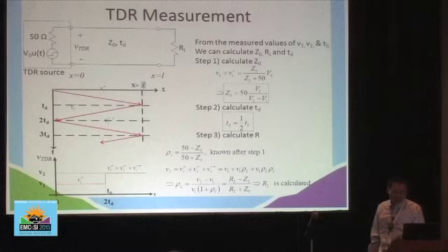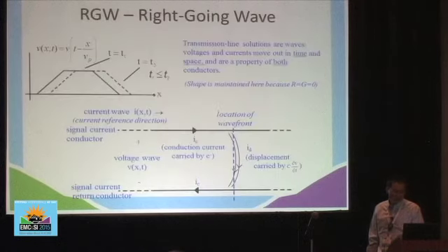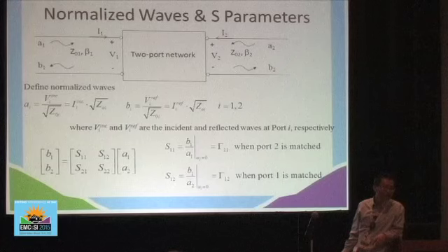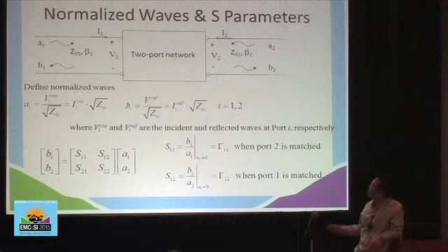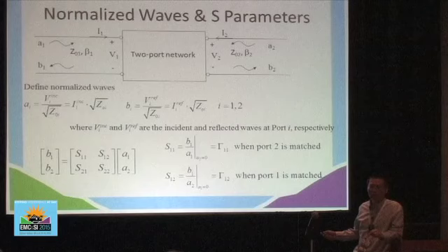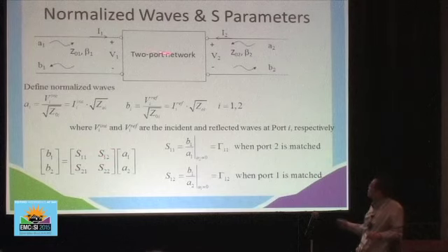The insertion loss and the reflection loss, that's a good question. It's actually a frequency domain concept. It's actually in here when we talk about the S parameters. Okay, so when you put some device into your measurements, if you see a reflection at one of the ports, if we take the log definition, we usually call it the return loss. Okay, so 20 log 10 of this S11 is the return loss. And S21 or S12 is called the insertion loss, which describes the loss from one port to another port, okay?